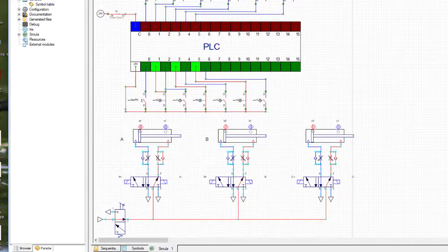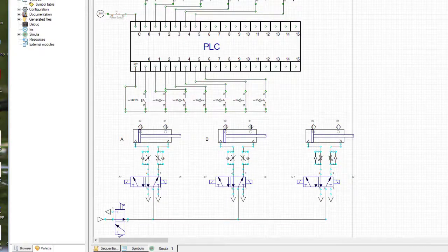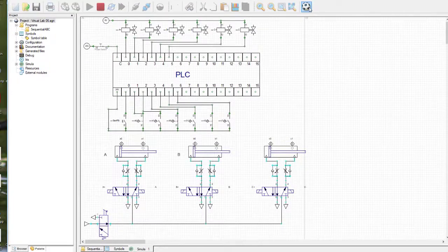Great. Okay, now I have to make one more addition, so I'm going to stop Dynamic Display, hit the stop button here, and unconnect. What I want to add to this is a reset button, because when we're doing this troubleshooting exercise, there are going to be points where the process is going to get stuck partway through, and if you don't have a way of resetting the outputs back to off, there's no way to restart the program.